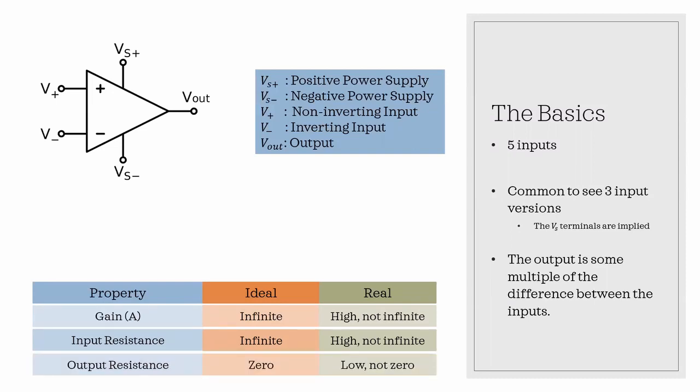So these properties are vital in analyzing op amp circuits, as well as troubleshooting any issues that might come up in constructing or analyzing our circuit. So let's look now at a couple of different configurations of an op amp. We're going to look at the open loop gain. We're going to look at inverting and non-inverting operational amplifiers. And then we're also going to look at the Schmitt trigger, which is a positive feedback trigger.